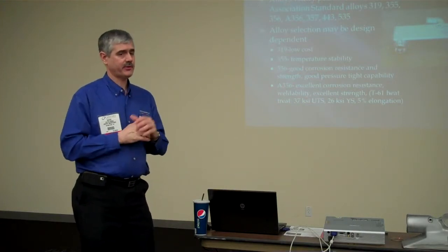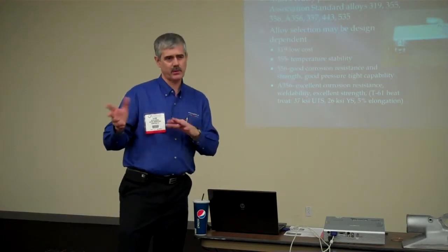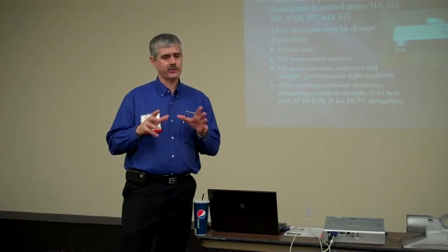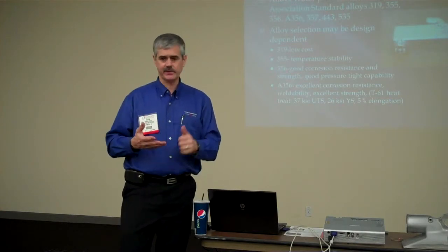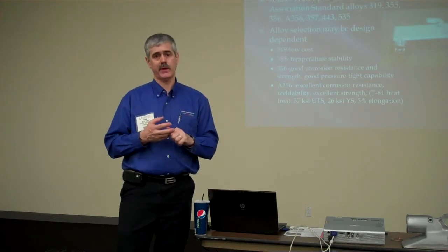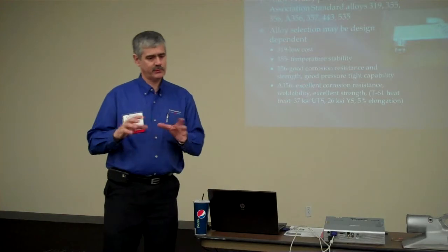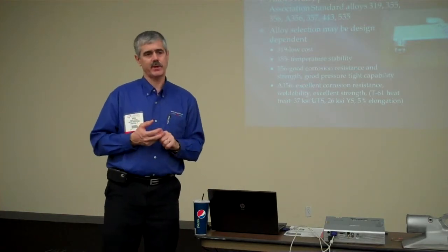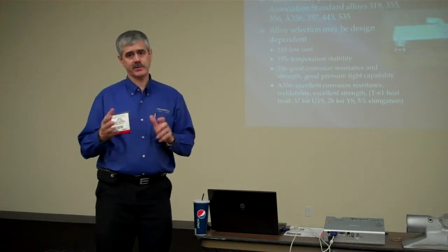One thing about alloys is the 300 series aluminums are all aluminum silicon alloys with around 7.5% silicon, and that's critical for the fluidity. There's other alloys like wrought alloys, 6061, 5052. Those are not castable. They have very good properties, but you really can't melt them and pour them into a mold. For lack of fluidity, typically is the main problem. So most common castings are in the 300 series, but there are specialty alloys too.